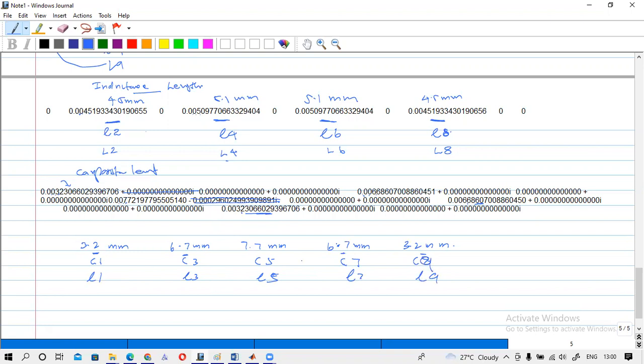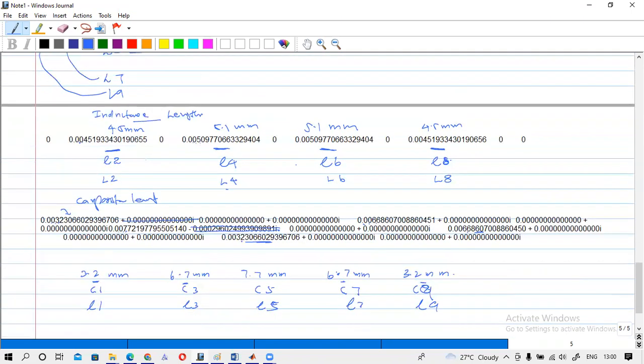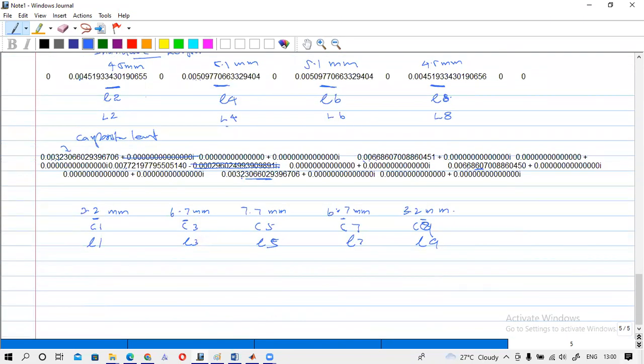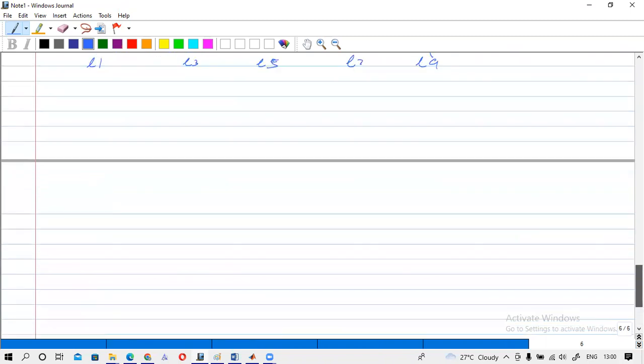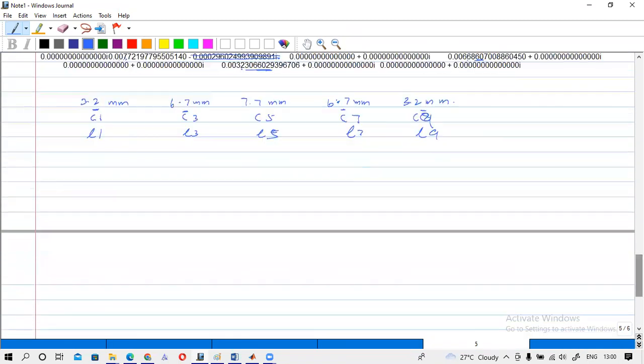So we have calculated the width and the length also. Then how to design this? So you can make the appropriate microstrip lengths on the given substrate, using this length and width. If I draw the layout, it is like this.